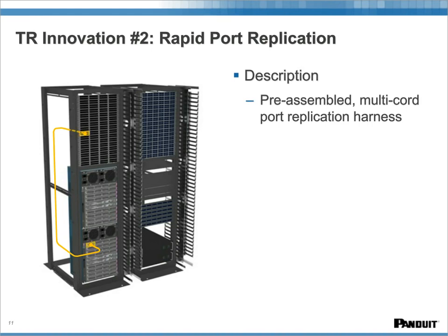Okay, so I've got the slide out about the port replication, and actually, what we're talking about with port replication is something which is incorporated in the TIA standard under the framework of the three connector channel. The TIA 568 C2 standard lays out three different allowable channels, those being 2-connector, 3-connector, and 4-connector channels.